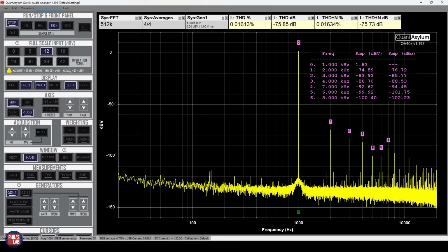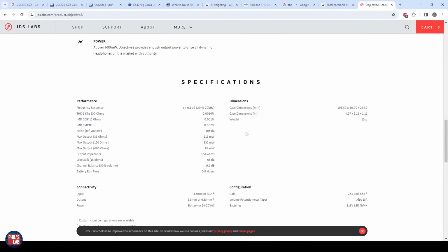And keep in mind, this is for a particular frequency at our input and for a particular input voltage or amplitude. This is also unloaded, so our system is only loaded by the probe and the input impedance of the QA403. So that might affect performance as well. So here we can see we're getting fairly reasonable performance for this kind of guitar effect amplifier, but compared to, for example, a rather high performance audio headphone amplifier, we're an order of magnitude off, so to speak.